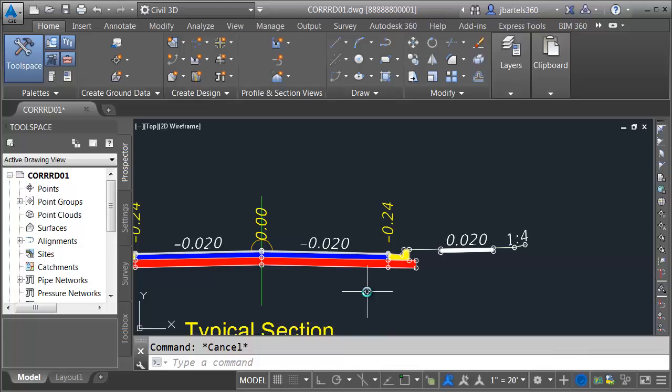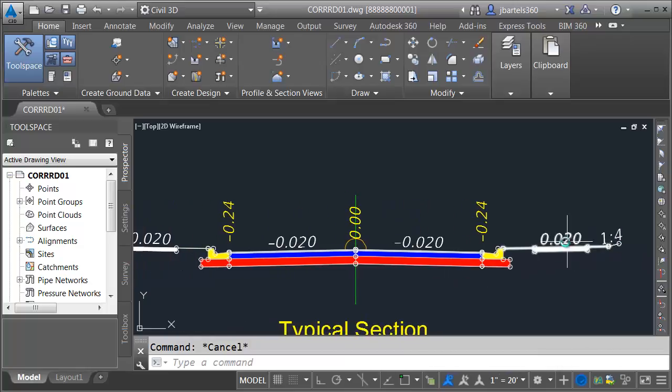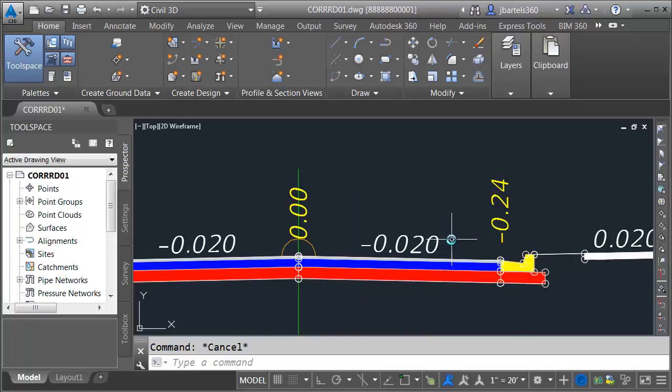The other thing the links are used for primarily is building surfaces. Back in the day, using some other CAD packages, we might have to trace the top of this object and use that to create triangles for a surface. Here, I can build the corridor, and I can go through and tell Civil 3D, I want you to build a surface from this corridor, and I want you to triangulate to any link that contains the top code. And then it automatically knows what to connect to because all of those links have the codes on them already.